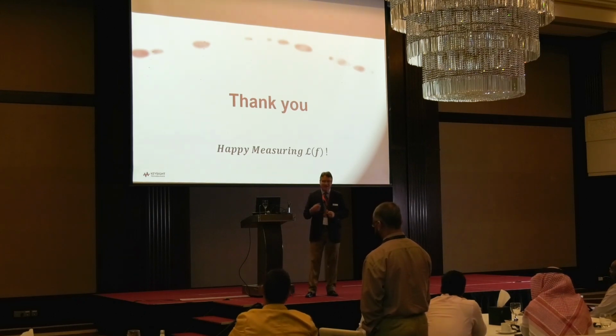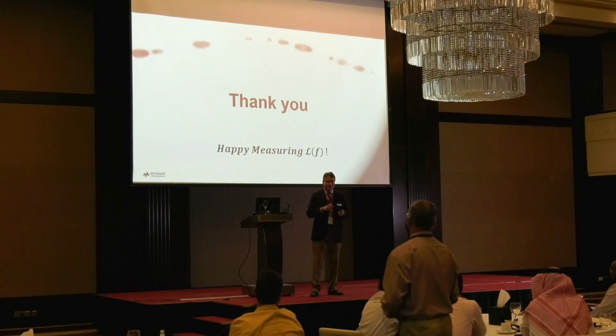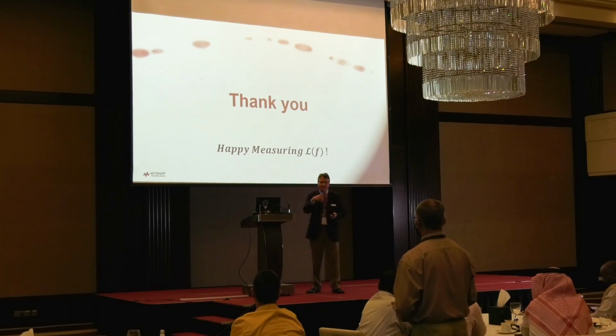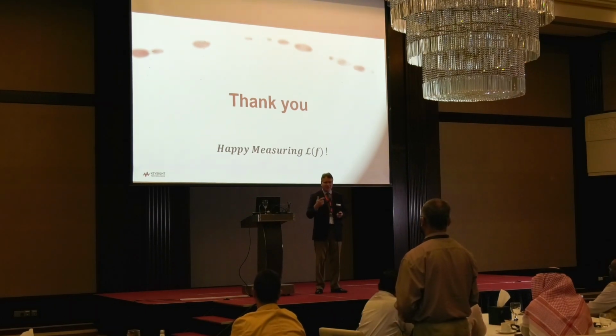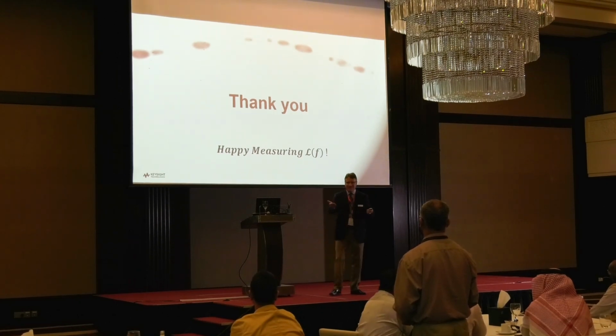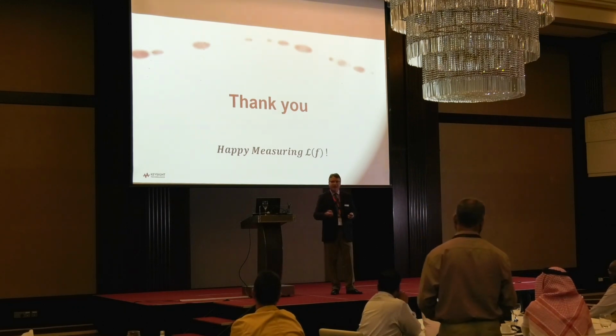So I skipped a couple of slides in the paper. There's another technique called FM discrimination, where we actually use delay lines to be able to deal with larger phase deviations, rather than using a phase detector. Maybe I can show you during the break. It is useful for measuring devices that generate very large variations in phase. But for obvious reasons, we typically don't want those kinds of devices in our system. So in most cases, we are talking about narrowband phase modulation analysis. That's where the techniques I showed today are more applicable.